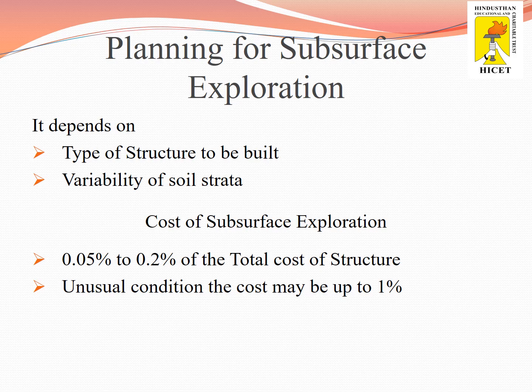So the next slide is planning of a subsurface exploration. In this topic, we decide how we are going to plan a subsurface investigation for a proposed site. It purely depends upon the type of structure we are going to build, and also depends upon the variability of soil strata available at the site.